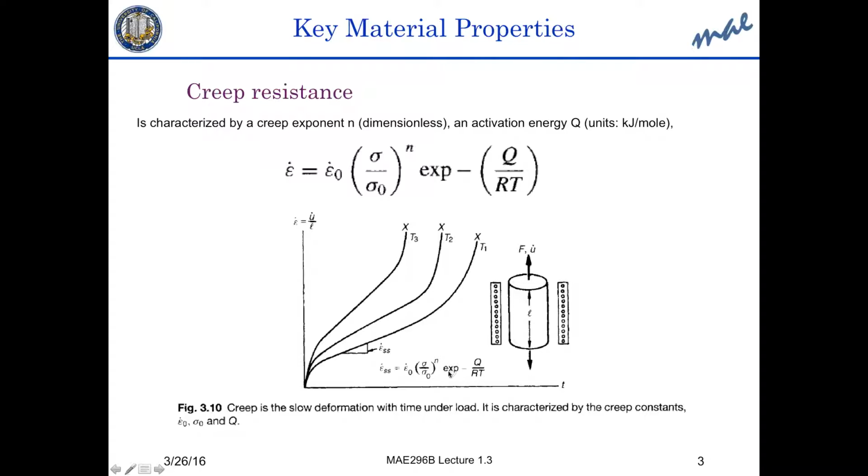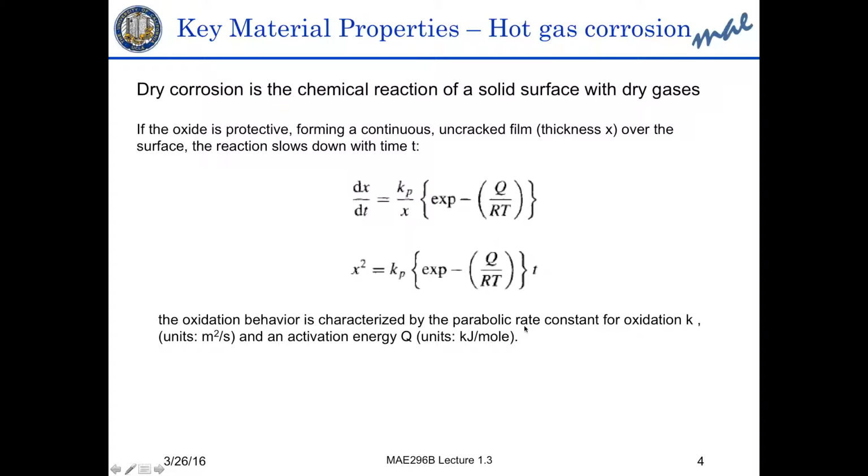So with these four constants, we are able to describe the creep rate. If we have this equation, we are able to describe the deformation, at least in uniaxial loading, and then as we will see later in the course, how we use such relationships in multi-axial loading.